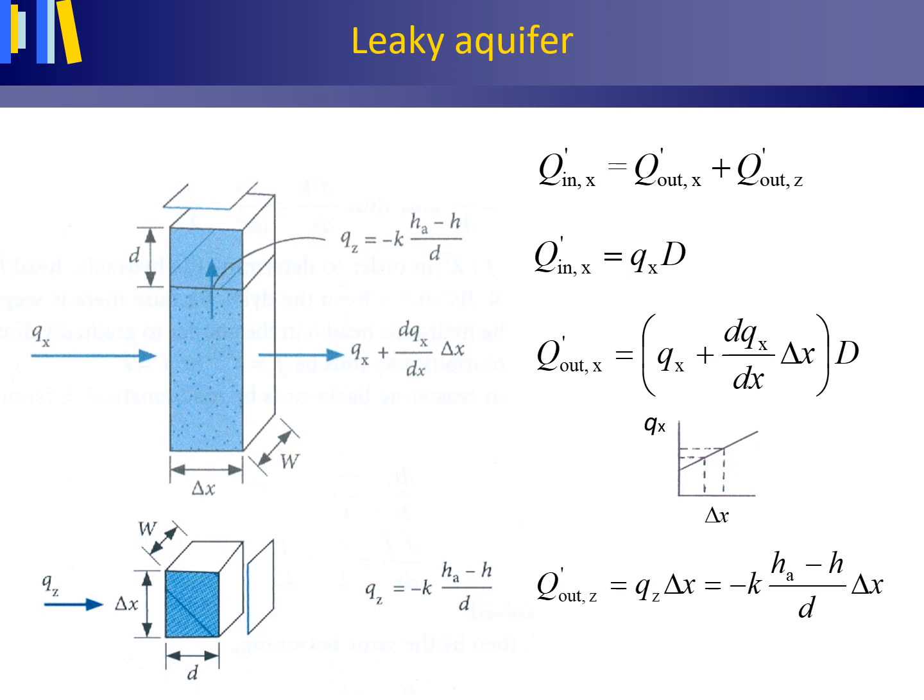Darcy's law for the aquifer can simply be written as Q with a prime in the x direction equals minus the Kd of the aquifer times the hydraulic gradient. The hydraulic gradient is the slope of a tangent line touching the potentiometric surface, the earlier dashed line, at a chosen location x. In this Holland's profile, the hydraulic gradient diminishes to the right.